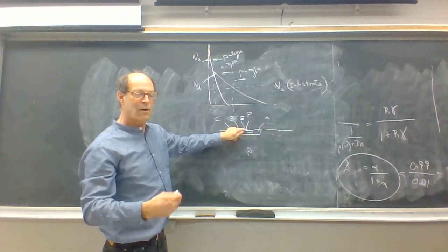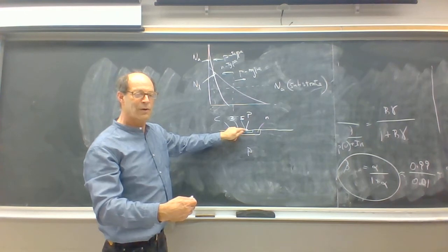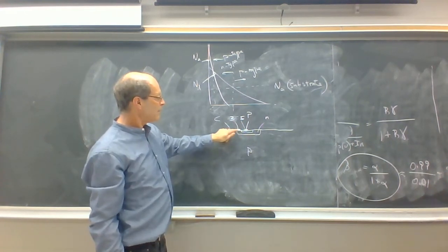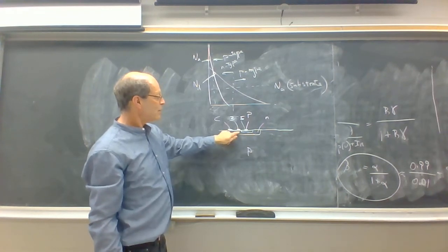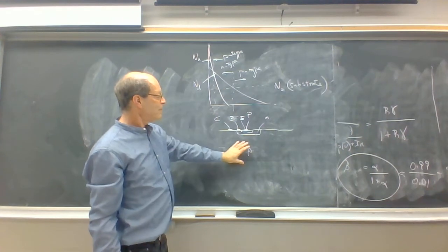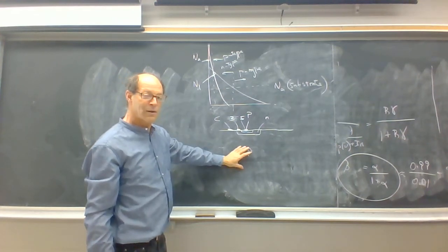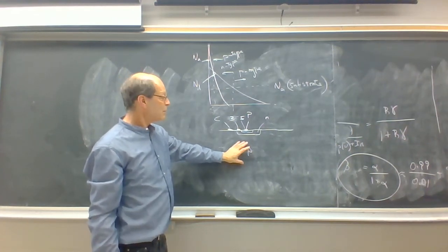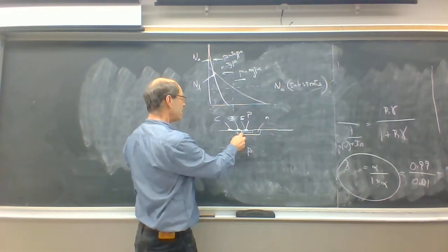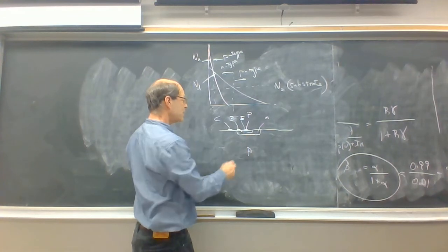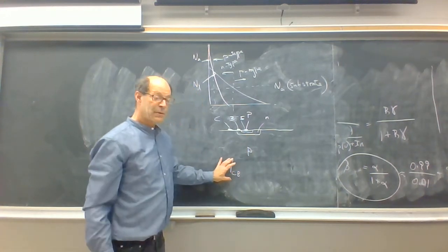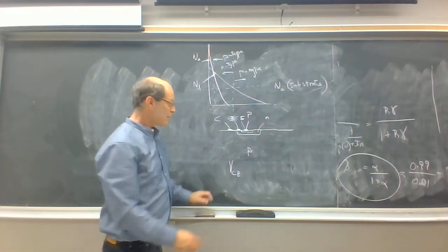That means high hole flow relative to a low electron flow in the base. The base layer has a certain level of doping, not too high and not too low. The collector region has a relatively low doping level, which is good because the collector base junction will have a reverse bias.